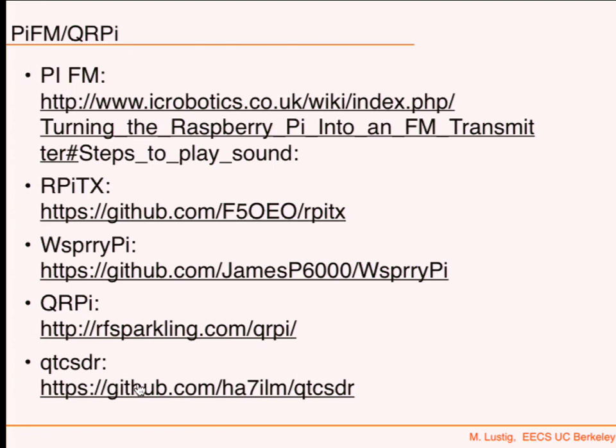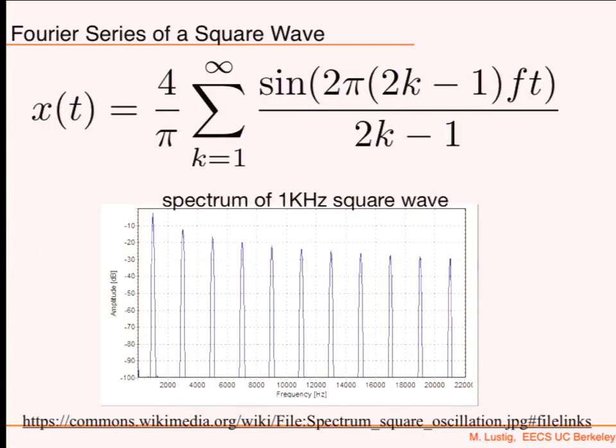Okay, so you can take a square wave as something periodic. You can compute a Fourier series of a periodic signal. If you compute a Fourier series, you realize that it's just a sum of sinusoids at odd harmonics with some coefficients to them. So there are going to be some harmonics generated, and those harmonics, of course, decay at a rate of 1 over the odd harmonic number. So there are a lot of very strong odd harmonics. So that would be illegal and problematic to transmit with this device by creating so much spectrum.